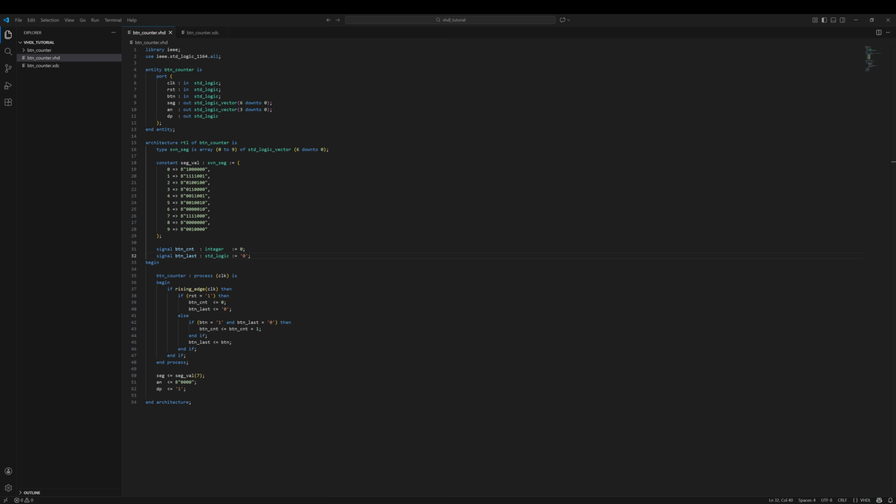But what if we want to display values that don't have repeating digit values? For non-repeating digits, we need to quickly shift which anode is on. If we do this quick enough, it gives the illusion that all the anodes are on concurrently. Now let's implement the logic that controls the anode and segment values.